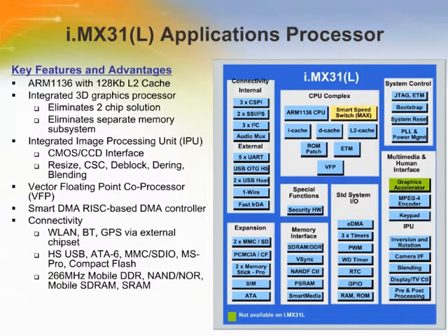The CPU of the i.MX31 is an ARM1136JF-S core based on the ARM version 6 architecture, supporting up to 532 MHz speed with a 6x5 crossbar switch, allowing for up to 5 simultaneous transactions on the 133 MHz system bus. The i.MX31 supports a number of lower power modes, as well as active well bias and power gating.